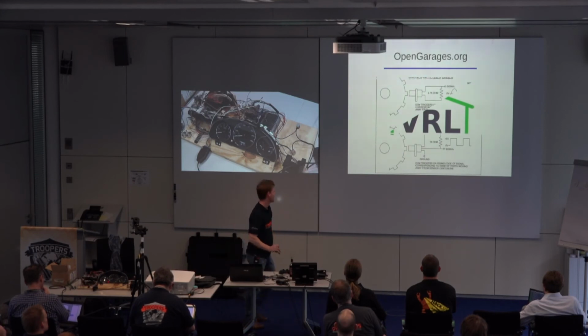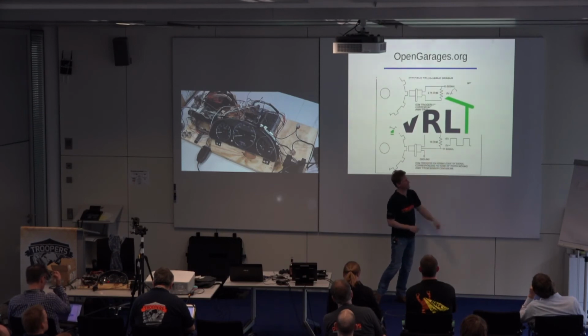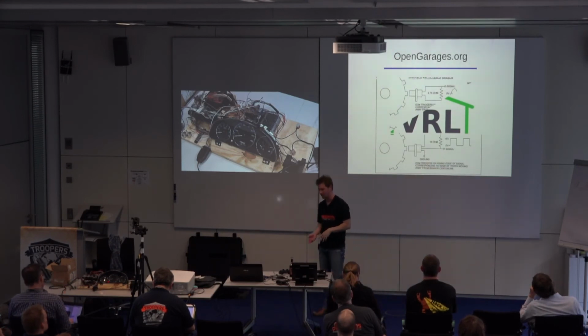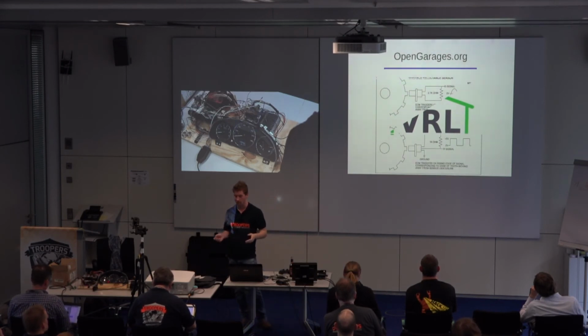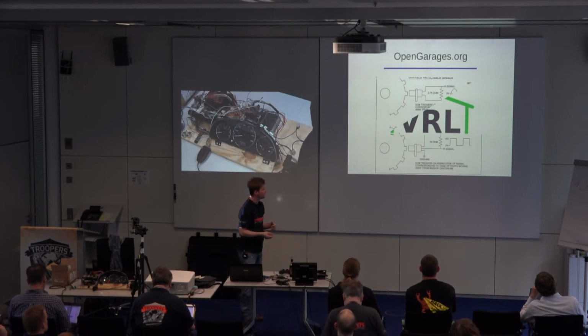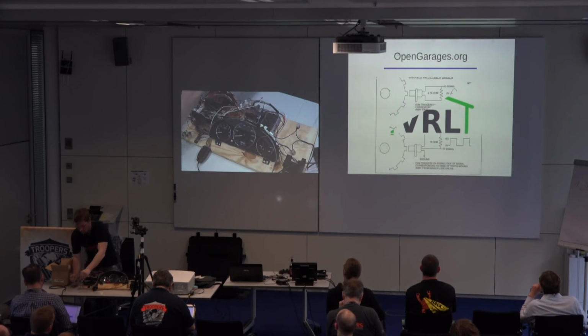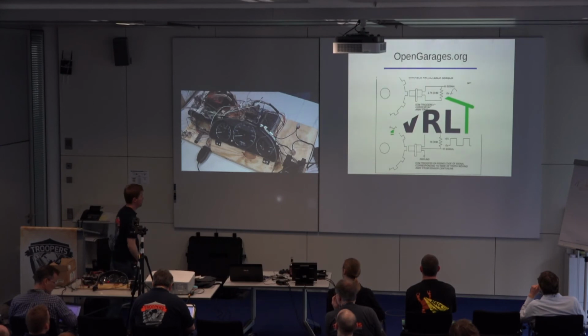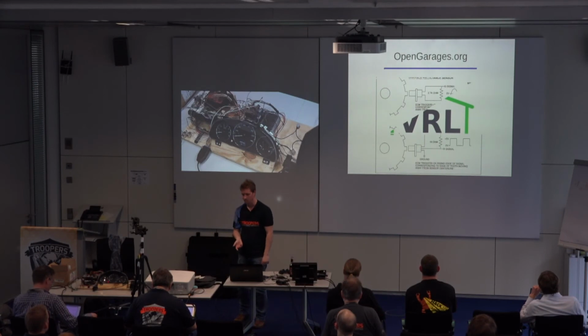I have no idea what's going on with this display right now. But that's an analog one at the top, and this is more of a digital one at the bottom. And it varies as to which one your car is going to use. But they're relatively simple to take an Arduino and simulate these signals. Either analog or digital. It's not a big deal. The speed is just how quickly they go by. So you add a potentiometer. I can't really see it on the screen, but I have one right here. Add a pot to an Arduino that simply controls the delay that is being sent to the crankshaft sensor, and that'll control your RPMs, sometimes speed.